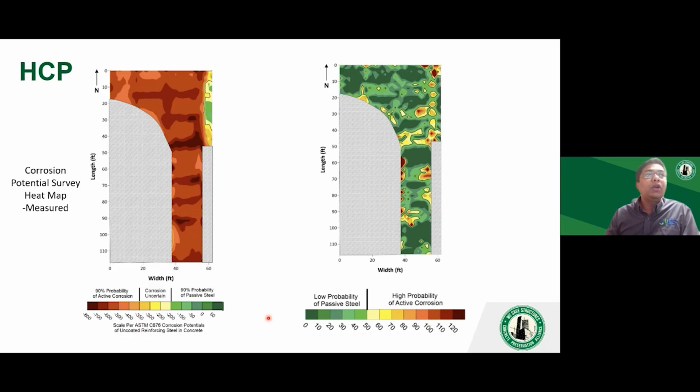And that's why you really cannot use these absolute potentials, because this is only applicable for copper sulfate reference electrode and steel in concrete. This ASTM 876 scale especially does not apply to zinc or anything else. It has to be applied to just steel. And that's where the delta potential measurements come into the picture. So it's all context: what are you dealing with? What are the environments? What are the different metal systems you're dealing with? And you need to analyze the data appropriately.